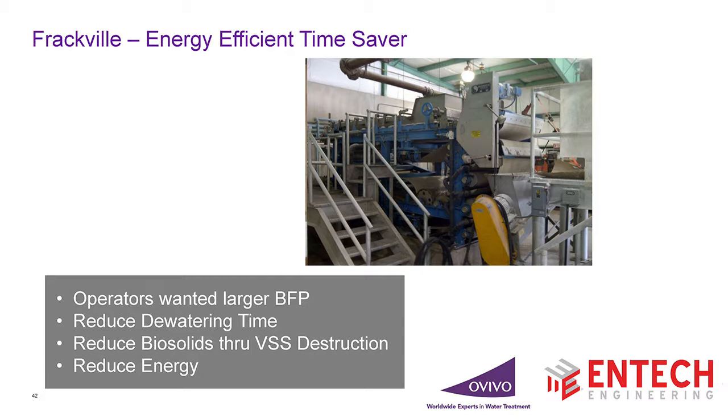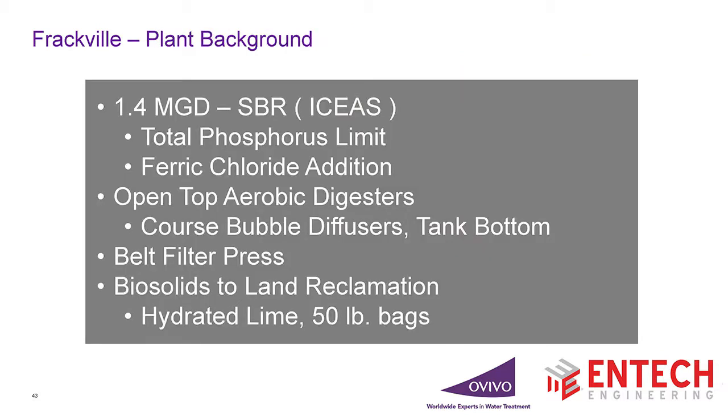So the operator said, well, the answer is we need a bigger belt filter press. I said, you really want to reduce your dewatering time. Why don't we try and reduce the biosolids through volatile solids destruction? Now, at this point, I had probably already done about 6 of these projects, and I knew what could be done. And I also knew we could reduce the energy. So the next one, Brian.